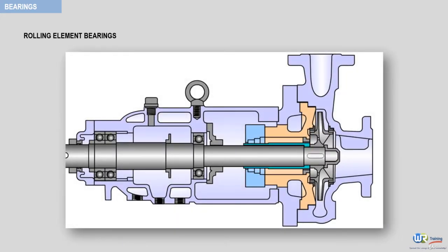With centrifugal pumps, the outer race that you can see here in red is stationary and is seated into a bore in the bearing housing. And the inner ring that you can see here in green mounts onto, centers and rotates with the spinning shaft. This arrangement may of course be reversed in some special duty pumps. Now let's see a 3D animation of a pump in service just to reinforce the understanding.